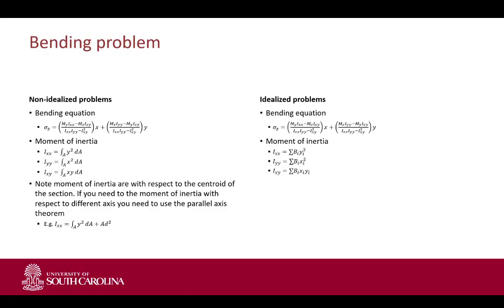Okay. So that's basically over. This is the most variation you can get over bending. And keep in mind, you're getting stresses. And of course, if you know an area, you can convert to forces. And then if you know forces and maximum force applied, or if you have stresses, you can go for failure to compare with respect to the limits, and make sure it's safe.